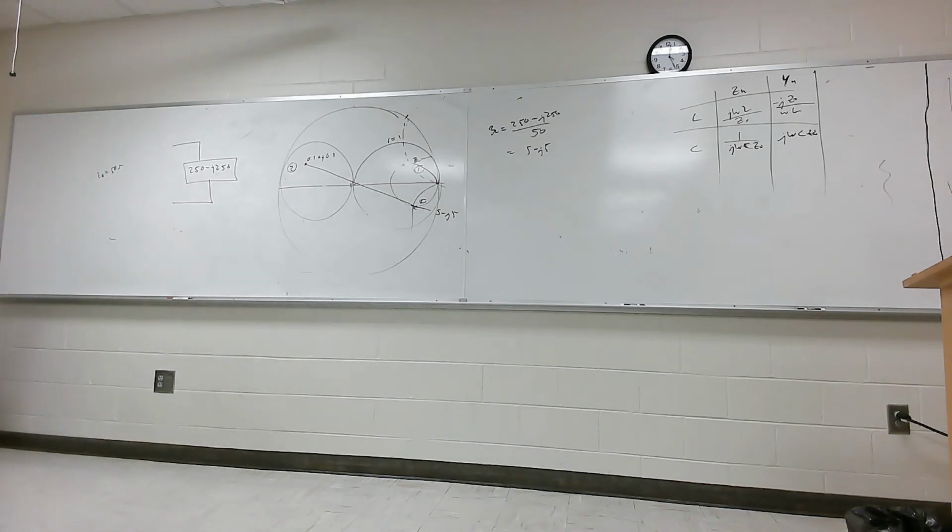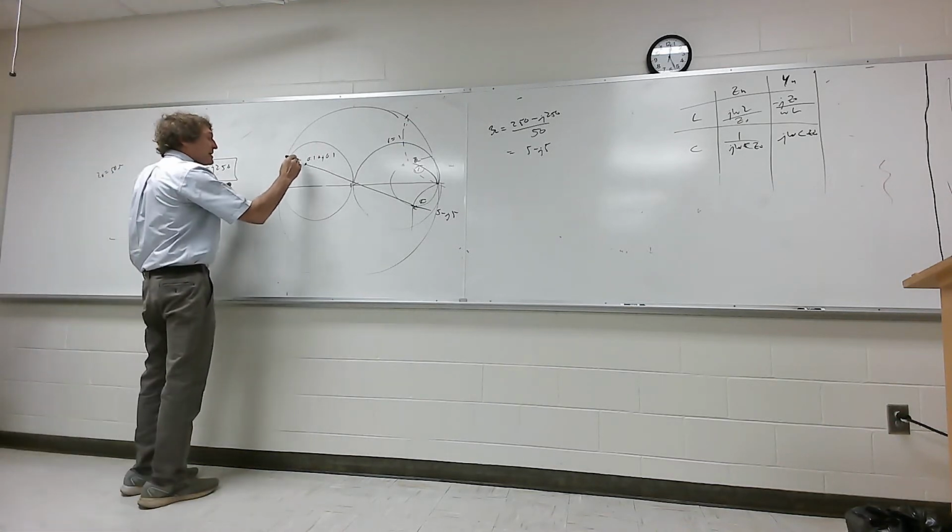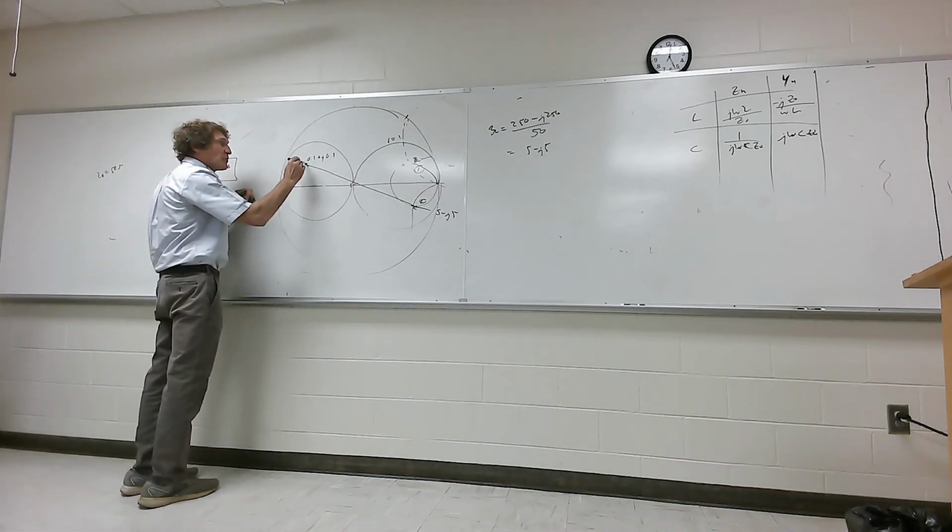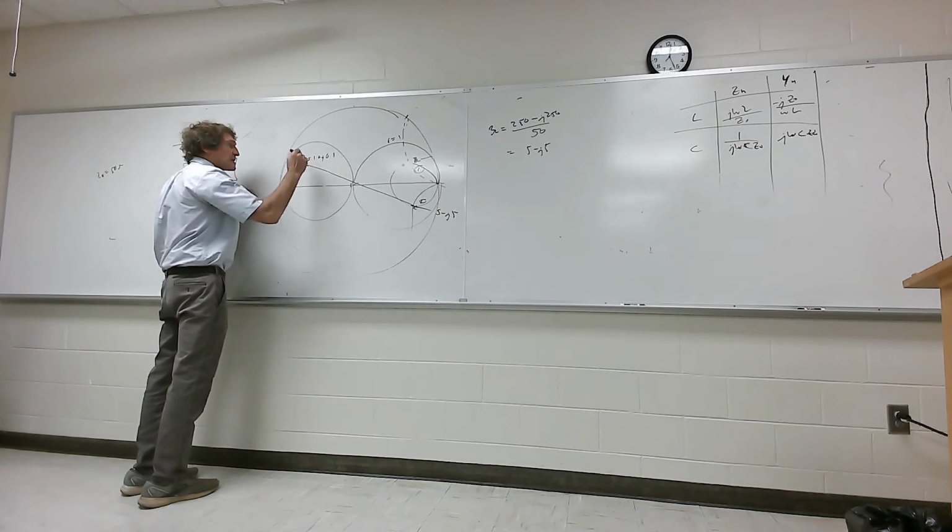I recommend you always add a capacitor in parallel, because we're in the admittance domain. This is going to be a parallel element. You all agree with that, class? And we're in the admittance domain, so we're going to go from here. Now the real value is 0.1, so if you take a look at that one circle,